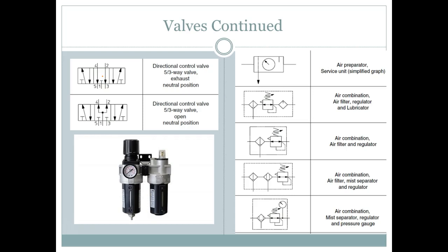Basically, if you don't regulate it somehow, that pump's going to try to build up as much pressure as it possibly can, right? You understand? So we regulate hydraulic pressure a little differently. We use what we call a pressure release valve. On a pneumatic system, we use what we call a pressure regulator. On a hydraulic system, we use a pressure release valve, which means it vents all the pressure above what you want, and it sends it back to tank.